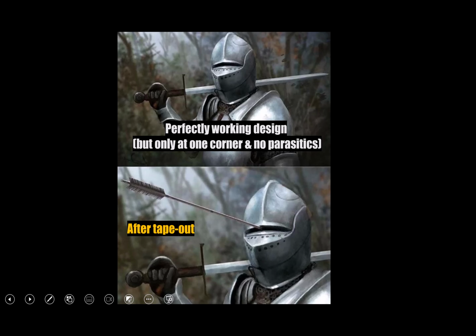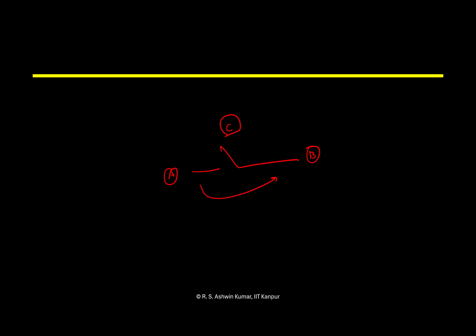Voltage control. That's all. Because remember, what is a transistor? Why is it called transistor? Yeah, it's a resistor. So it's basically trying to change the resistance, which means you want to make a switch. You want to control the flow from terminal, let us say A to terminal B, using voltage applied on another terminal C. This is essentially controlling the current through a voltage. So fundamentally, you are making a voltage controlled current source, right? So if you understand how to make circuits using a voltage controlled current source, you will always stay relevant even after 10-20 years. If a new transistor comes, the same circuits you can use with minor tweaks here and there.